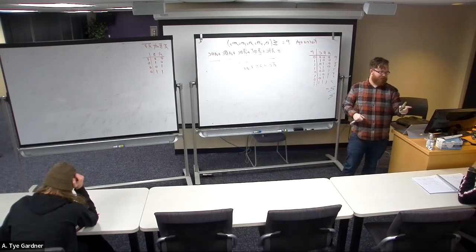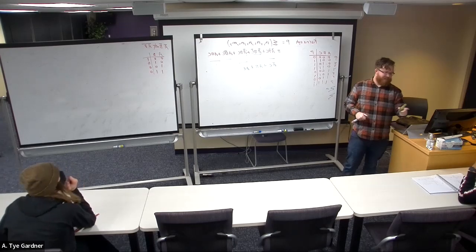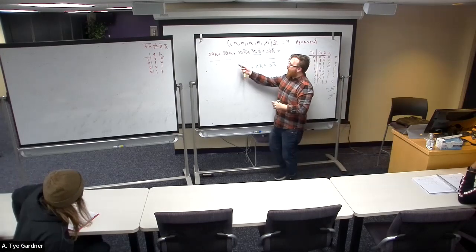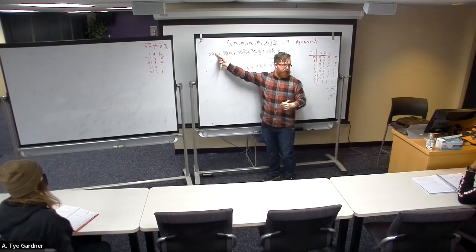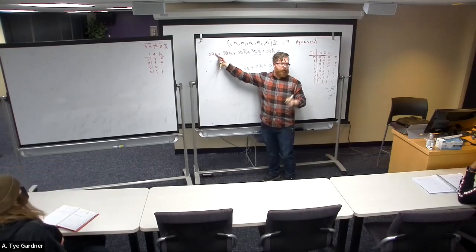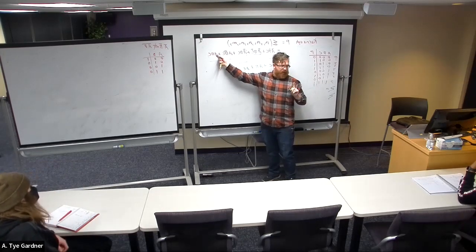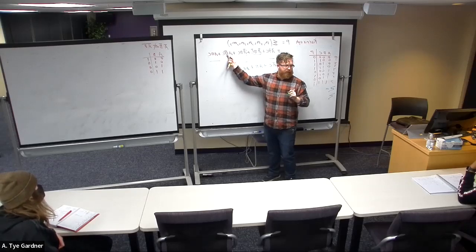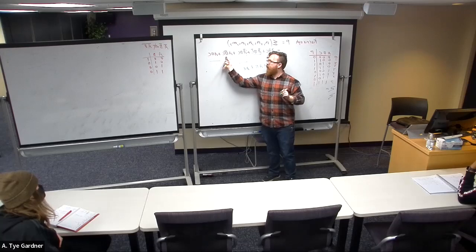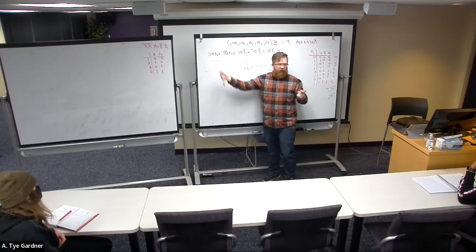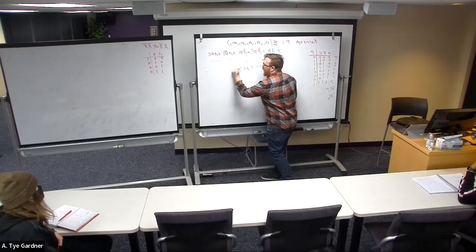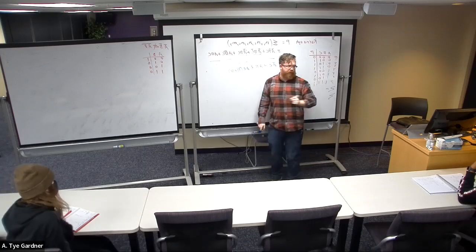I look scared and confused. A little bit. So all I've done in this one, each one of these is I've identified two terms that are logically adjacent, which means only one variable in each term is different. Right. So here, that's the B, because A, C, not B, B. B is what's different. So when I factor out not B or B, that's the only thing that's different.